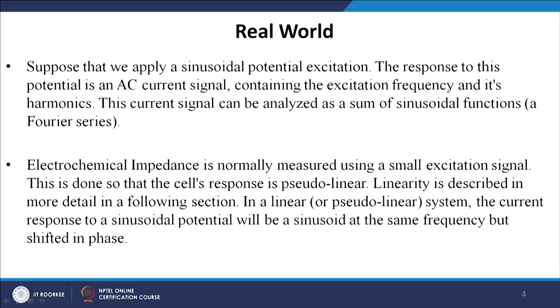In a linear or pseudo-linear system, the current response to a sinusoidal potential will be a sinusoid at the same frequency, but shifted in phase. So, basically this is why we prefer a linear system: if we apply a sinusoidal voltage, in the output we will also get a sinusoidal signal, only with a phase shift. It is not that I apply a sinusoidal signal and get a triangular signal at the output. So, that is the linear signal. It restores the shape or the information of the signal.